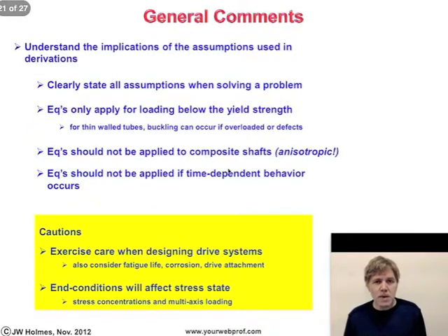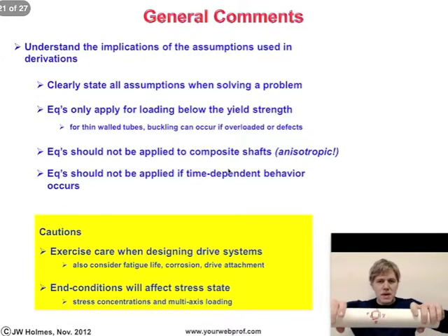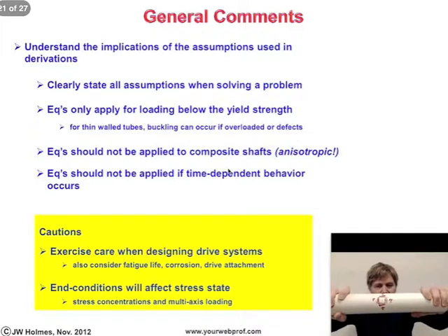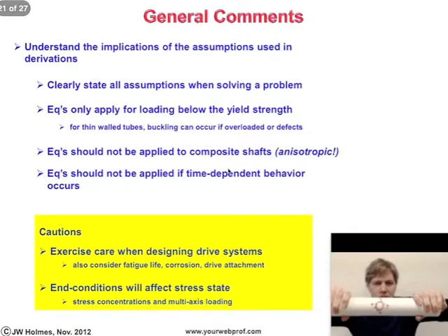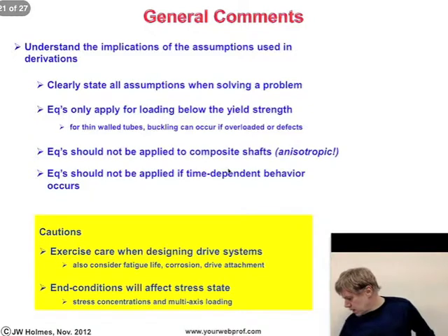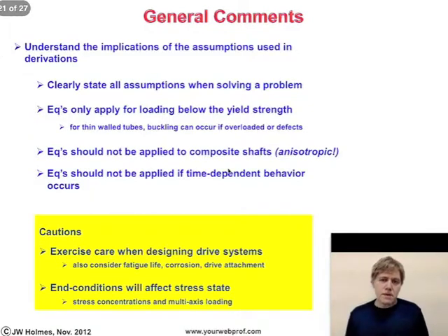We also have to worry about multi-axis loading. If I take this tube again, and I apply torsion, and I apply bending at the same time, or I apply compression or tension, that's going to change the stress state. It's going to change the fatigue life. We can handle those problems. If it's a fatigue problem, we can handle that through multi-axis fatigue theory. So it's not a big issue, and it's done every day. Otherwise, you wouldn't be able to drive a car with a drive shaft for very long. All right, so these problems have been solved, but for each application and each time you choose a material, you have to go back through and reanalyze the problem.